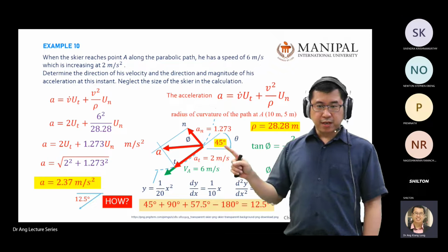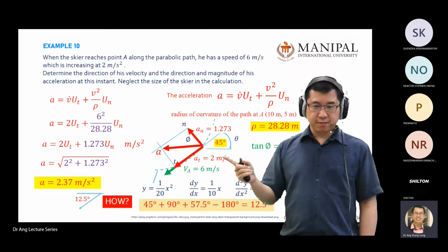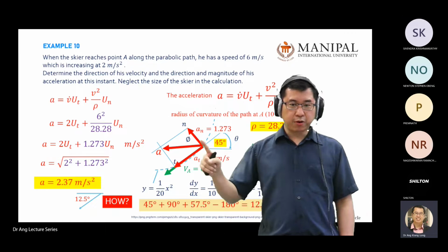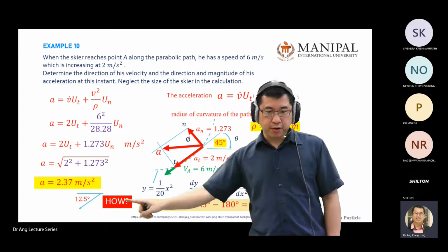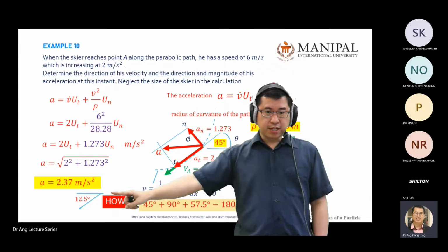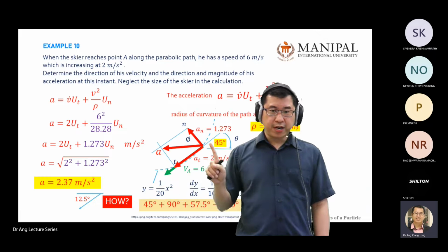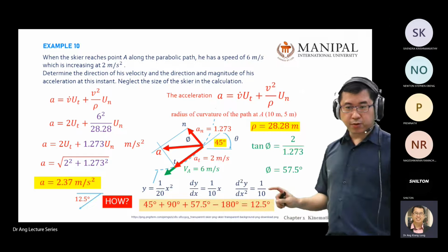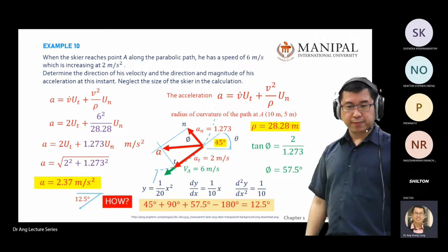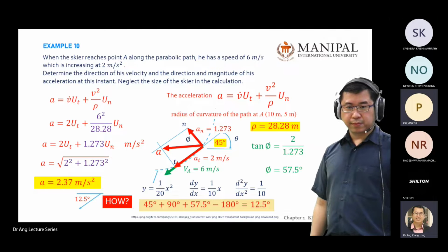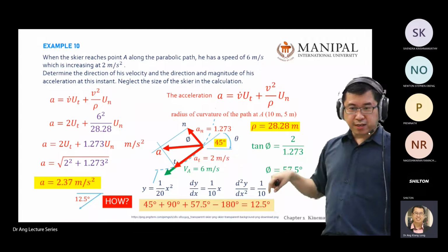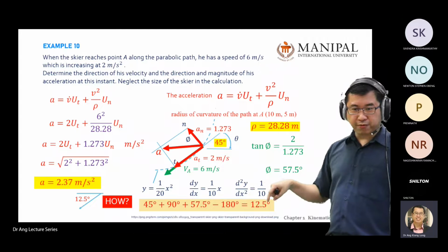Meaning, here, you rotate up to here is 192.5. Here to here is 192.5. What is the direction from horizontal? 192.5 minus 180, you get 12.5. Do you see this answer? Yes, sir. Understand, sir. Anyone still missing? You still blur how to find 12.5?